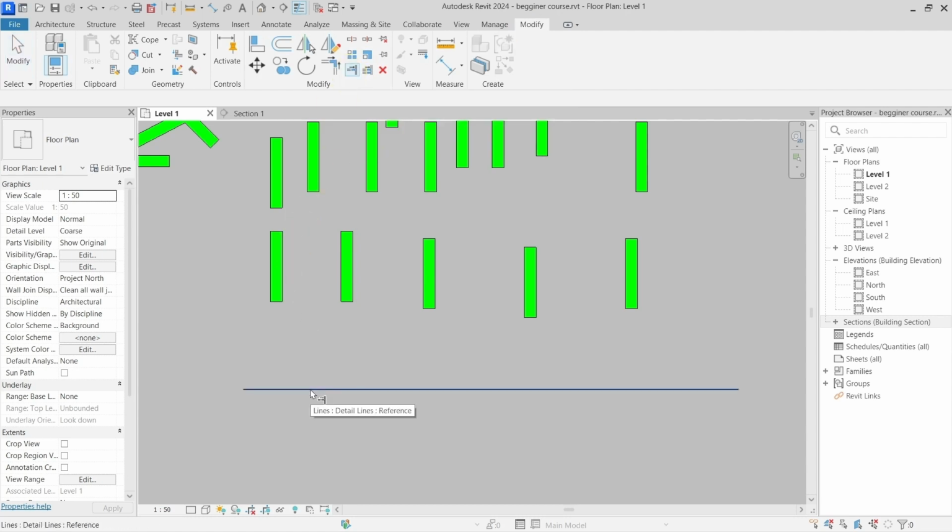first you will select the reference and then onto this reference you will extend this wall. You can see again the preview of what will be the result. If I do it, you can see that it enlarged the wall to meet with my detail line. I can go and do this one by one like this, but I need to always click first for the reference and then for the element I want to apply this for.